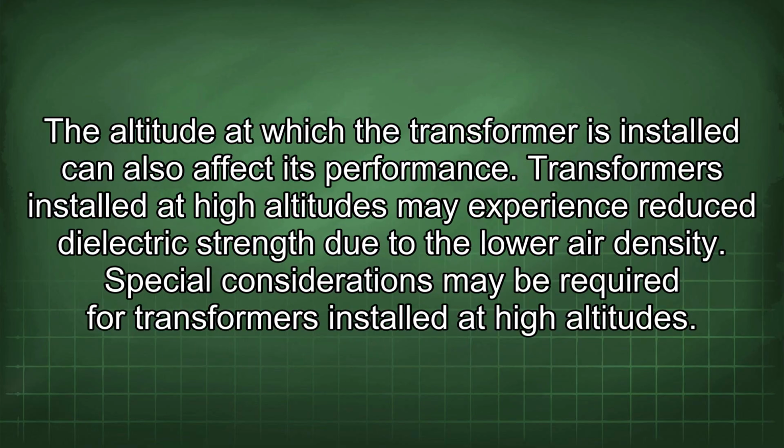The altitude at which the transformer is installed can also affect its performance. Transformers installed at high altitudes may experience reduced dielectric strength due to the lower air density. Special considerations may be required for transformers installed at high altitudes.